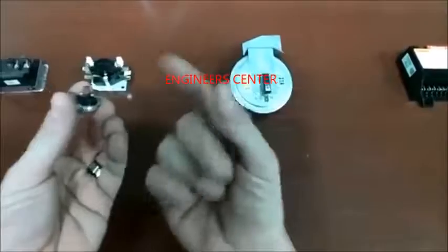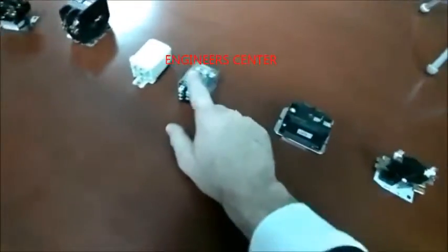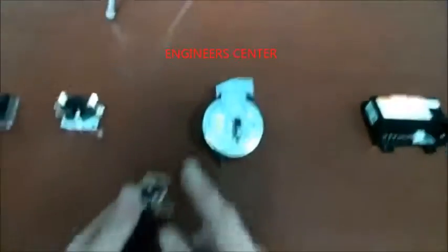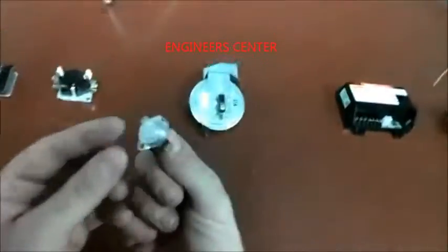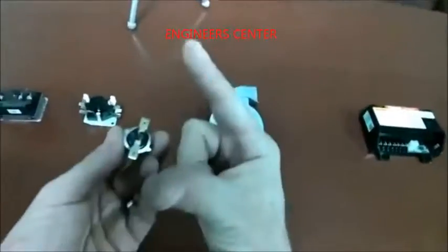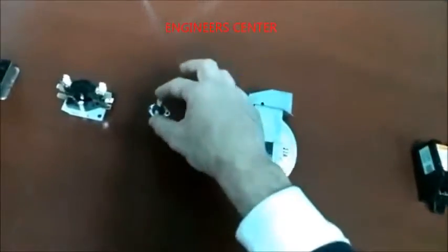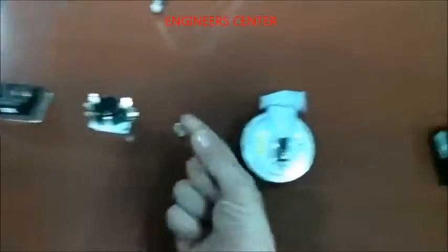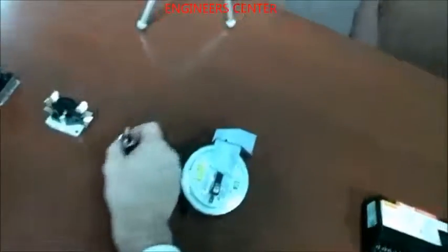This opens and closes also. It's really all anything ever does, is open and close. Some open and close due to getting voltage, like all these, and some, like this one, open and close due to temperature. And so when this senses that it's too hot, this will now open. So it's a safety switch, but in reality, it's just a relay that opens and closes from a different type of signal. It opens and closes due to heat.